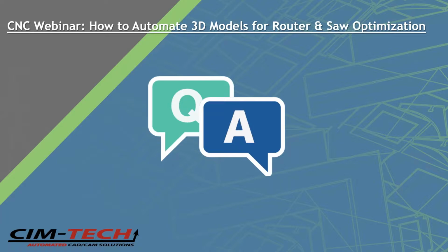Oh, that's a good question. So today we focused on how to do it from a 3D assembly, right? We took a 3D assembly and SolidSim ran through it and made a cut list, and then we filtered the cut list with SawSim. If you're going to use parametric macros, many times you import from an Excel spreadsheet or a CSV, and there you could have a column that says send to saw, and it will output those parts to a saw.